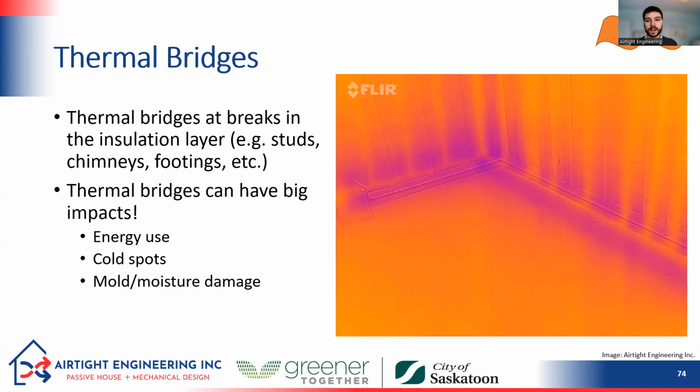And the last aspect of energy movement through a house that I want to touch on is an idea called thermal bridges. These are something that we haven't necessarily given enough thought to in our construction industry, specifically the residential construction industry. Often we'll put in a lot of insulation, but we won't think of the spots where we've got breaks in the insulation. So a thermal bridge is anywhere where there's a break in the insulation layer.